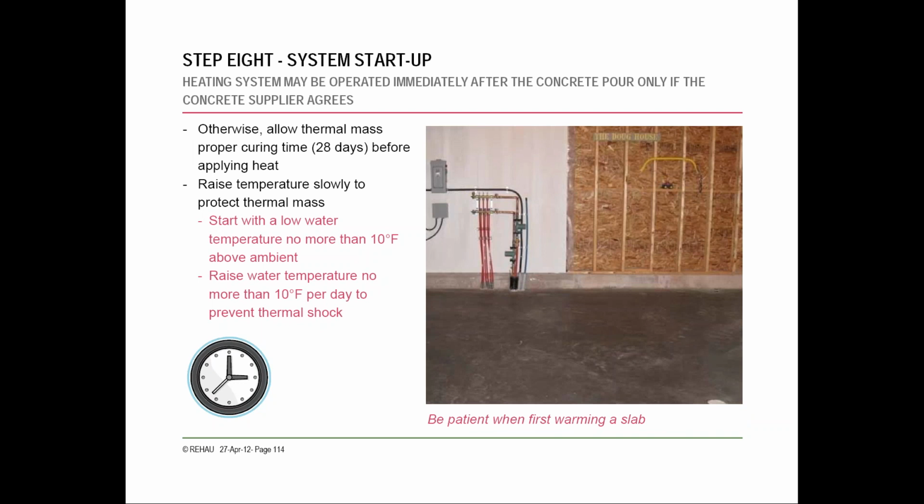After you get the system all installed and everything, you want to bring the concrete slab for the first time up to temperature very slowly. You don't want to just start running a ton of hot water at 180 degrees, or you won't want it at 180 degrees anyway, but you don't want to bring it straight up to temperature right away. So when you're first warming the slab, just be careful. Check with the concrete guy on how many days you need to let it cure before you can run any water through it.